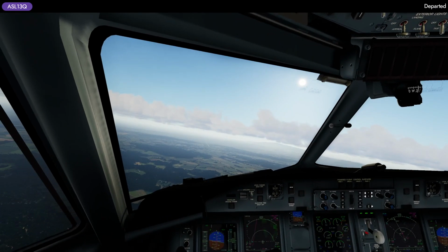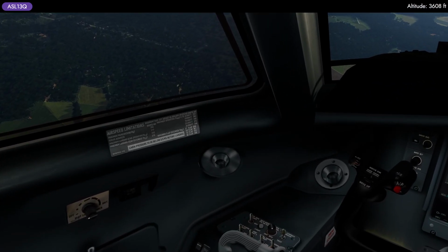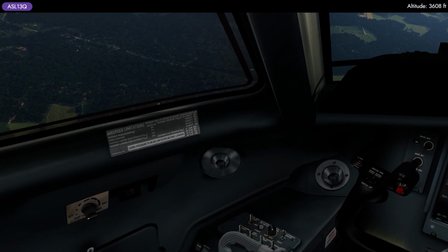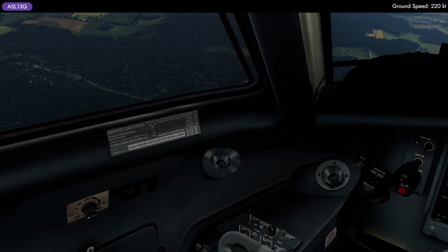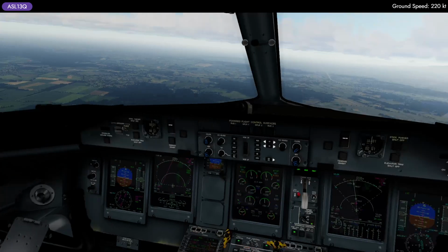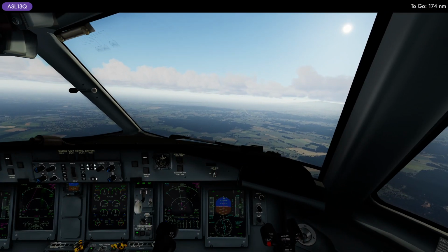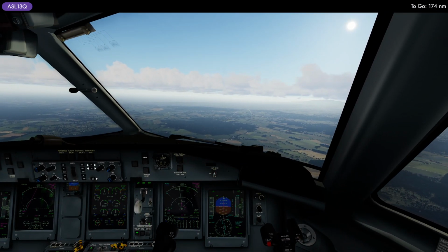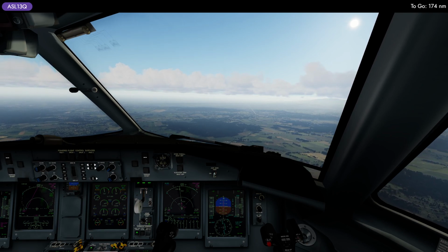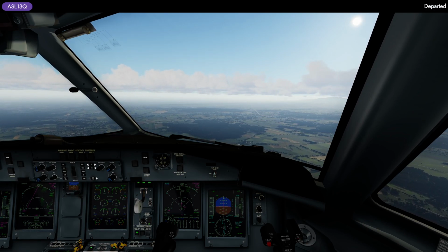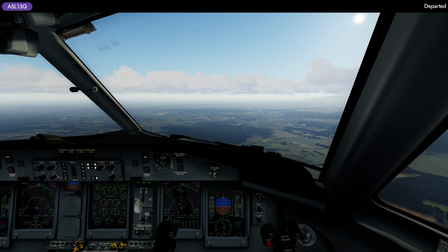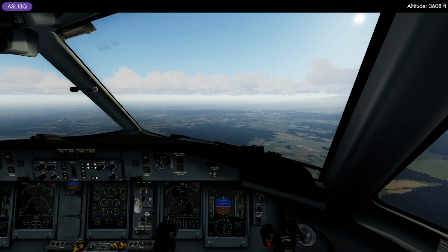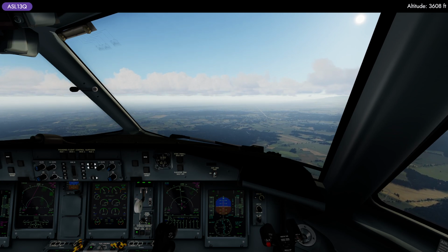I believe the operating speed is pretty high for the flaps, so we can go with flaps 200, 180, 170 and 160. We are already on 200, so once the glide slope becomes alive, we can actually extend to 5 degrees, then on 180 extend to 10 to 15, and then in the end to 35. So let's keep it around 200 for the intercept.